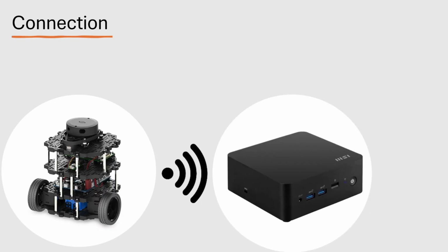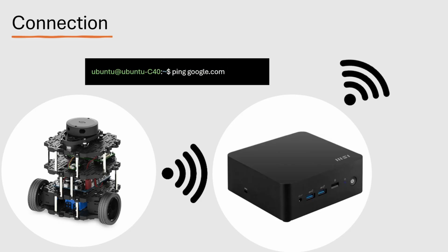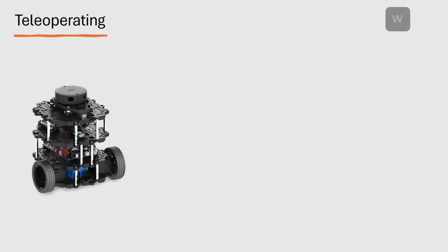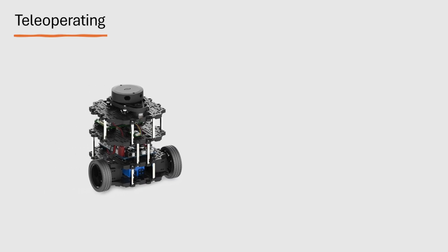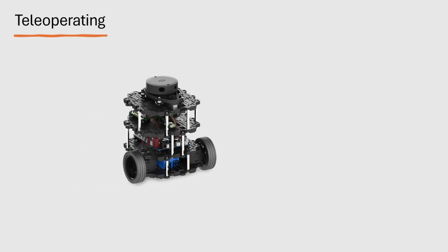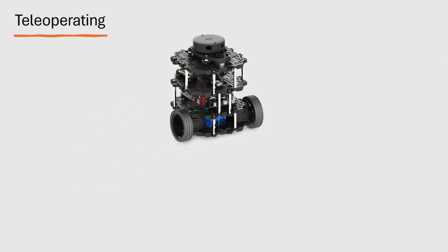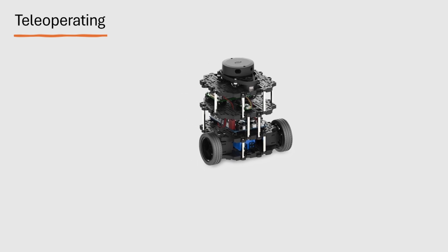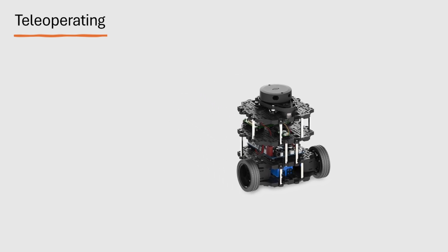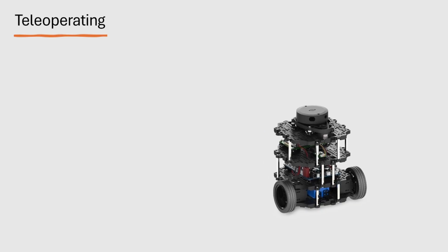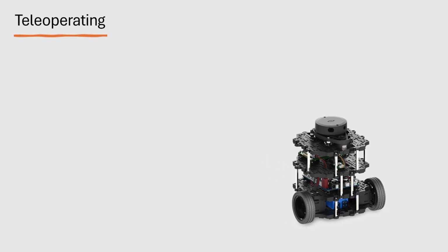Once we confirmed that the devices could reach each other on the network, which is something we tested using pings and reviewing ROS topic lists, we launched the familiar teleoperation node from the PC instead of the Raspberry Pi. Immediately, we could see the real Turtlebot respond to our keyboard input, driving forward, reversing, and rotating based on remote commands. This proved that the control, perception, and localization were all functioning over a distributed system.